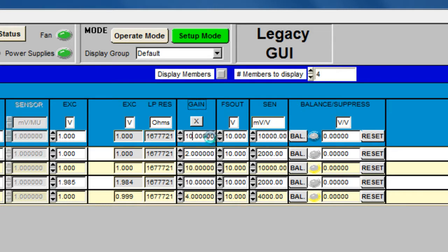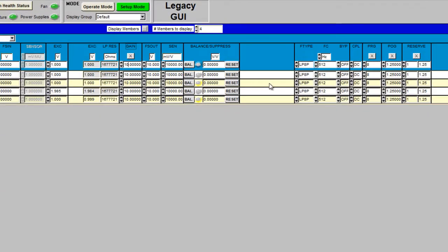By allowing some of the gain to be on the band-limited side of the programmable filter, the PFI amplifier allows some of the gain to be applied to the wideband input stage, which has both in-band and out-band energy, and some of the gain to be applied after the signal has been filtered. This allows for the overall amplifier gain to be applied to the in-band signal while preventing the amplifier from saturating on out-band signals that in some cases can be larger than the in-band signal.